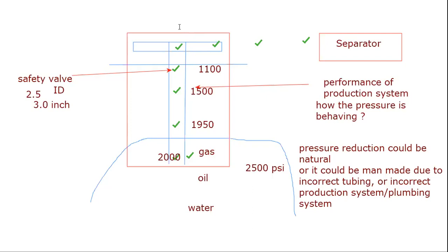For example, now there's 1100 psi and the equipment is, let's say, a safety valve. Which safety valve should we put so that this pressure loss is the minimum? This is our job. This is what we are looking at, and this is what we will try to solve. How we can select this safety valve, in this lecture and the next 3 lectures we'll continue talking about this.